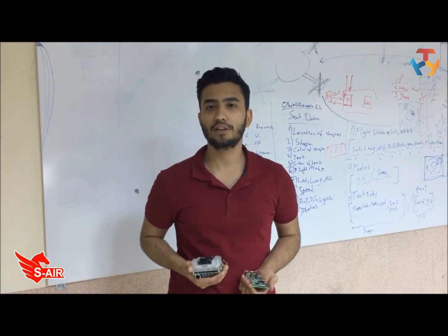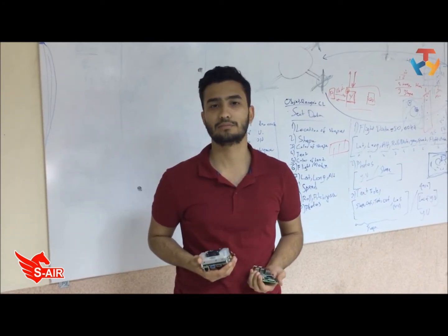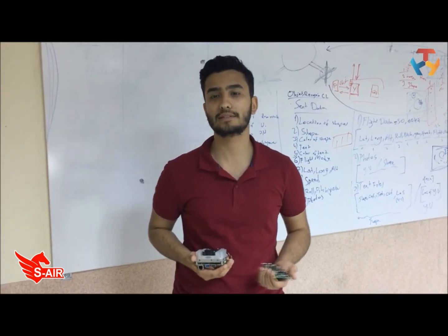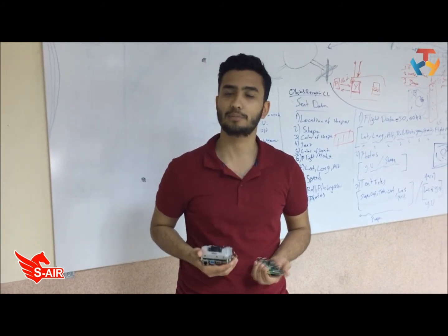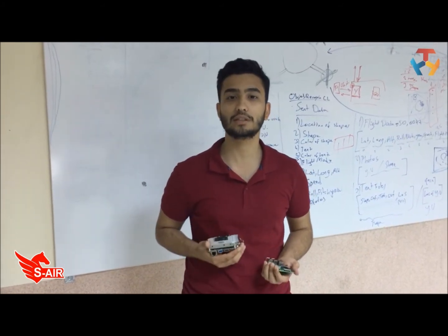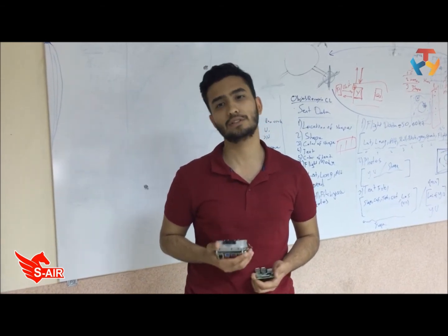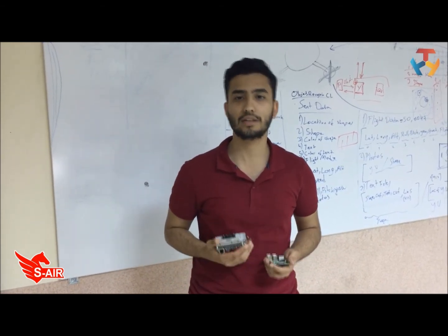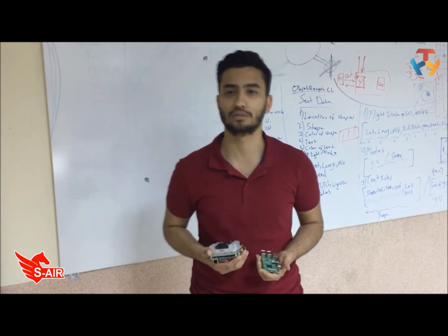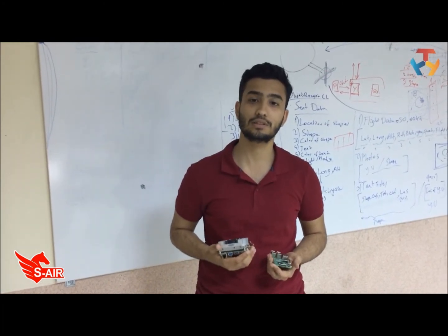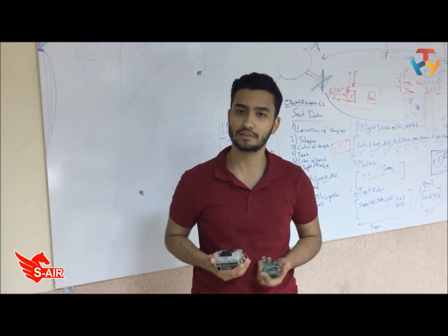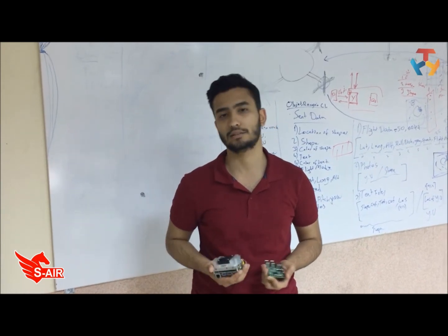While designing the UAV, a companion computer is used, and there were many choices for the embedded system card. Our choices were Raspberry Pi 3, Asus Tinkerboard and NVIDIA Jetson TX2. These cards were compared and their sufficiency was tested. According to the test results, Jetson TX2 is chosen. The main reason for choosing the Jetson is that it is way faster and more stable than the other cards.